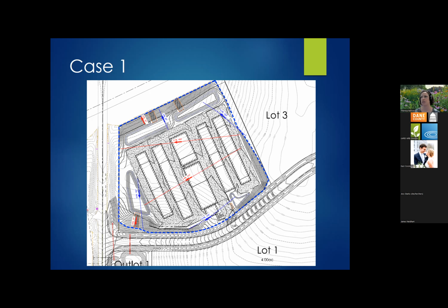this site, since there is a variety of slopes and slope lengths, both in the existing conditions and then the proposed conditions. So looking at our slope number one, the blue line represents the existing conditions. So again, that condition that occurs when topsoil stripping is taking place, but the mass grading hasn't happened yet. And then the red lines are the condition once that mass grading is complete.